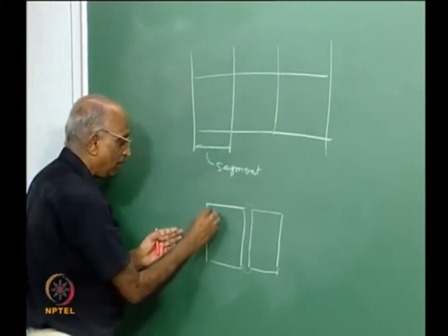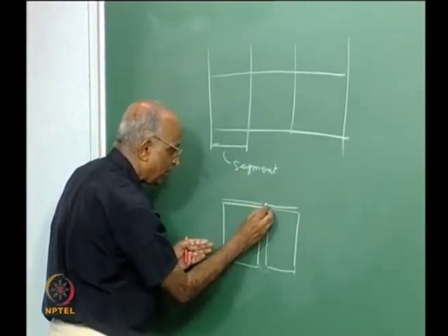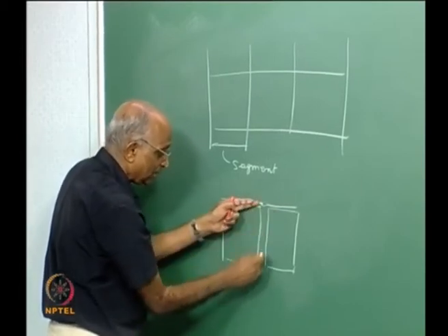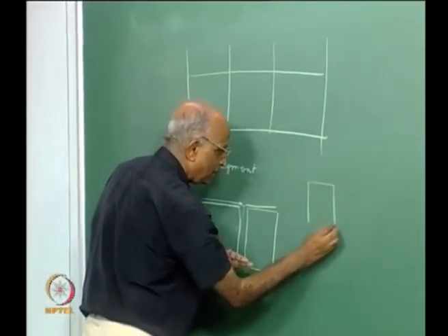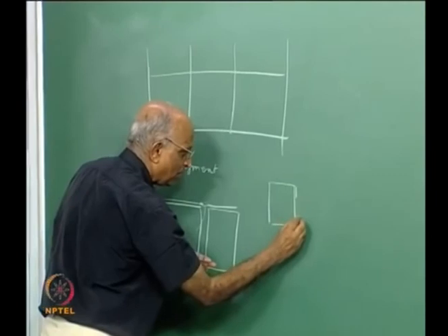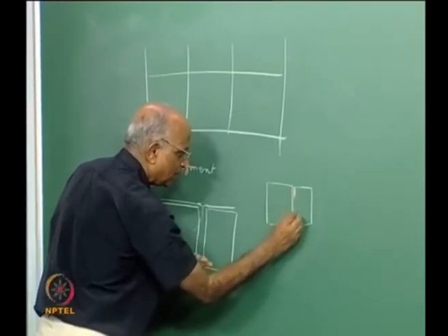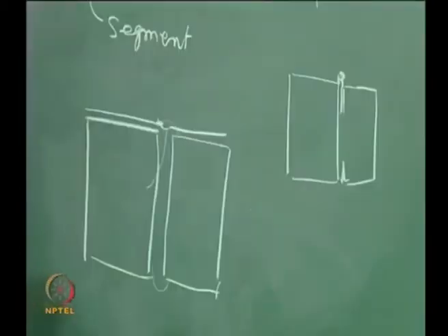How do you assemble it? You have the case over here, you have the case over here. You need to make sure that these 2 are joined together such that no leakage is possible between them. In other words, for one segment, maybe I will put insulation over here, then I have to put the other segment over here. This has to be joined together, maybe in some form over here. And how is it joined? We put O-rings.